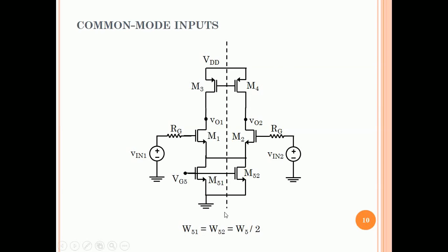Earlier when we did low frequency, I had done RO5, right? We had done in fact 2 RO5 here and 2 RO5 here. So how is that 2 and this is divided by 2? Because if the width is half, the resistance is double. Alright, but now we are saying transistor, not resistor, because we have to account for the capacitances also of the tail current transistor. So that's why we divide this circuit with the transistor itself.